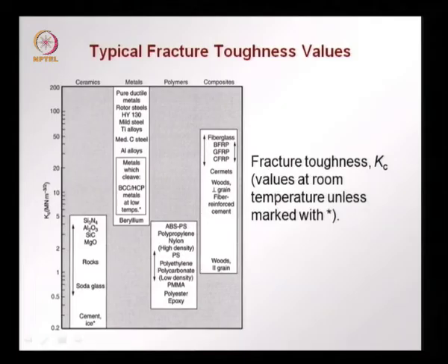We can look at a table of values of fracture toughness. We see that the values for materials that we always think of as brittle, like glass, cement, ice, rocks, other ceramics, are lower, the fracture toughness is low. So, that is why these materials crack rather than yield. On the other hand, we have metals, ductile metals, the pure metals are most ductile right at the top, where the fracture toughness is so high that these materials also always yield, they do not crack or rupture.